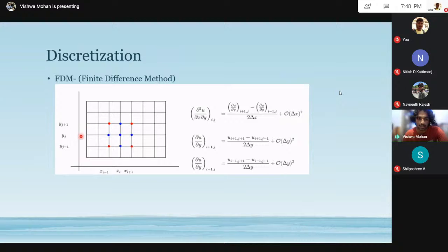So just concentrating at this particular point. In finite difference, you just split it into grids. Don't worry. You get this point and you need neighboring points. So we just do everything in the interior. We don't go for the wall points because we need to specify boundary conditions.